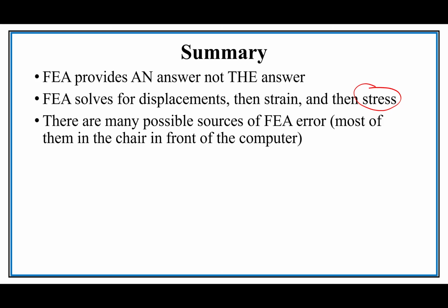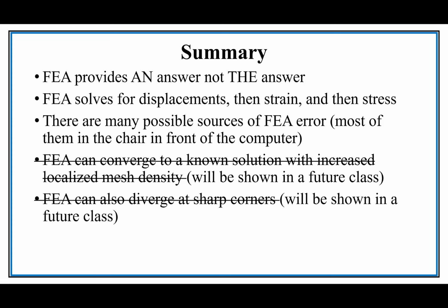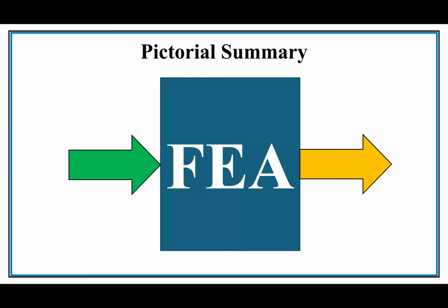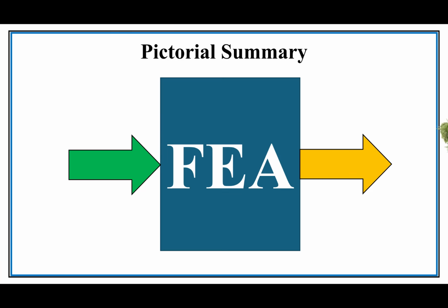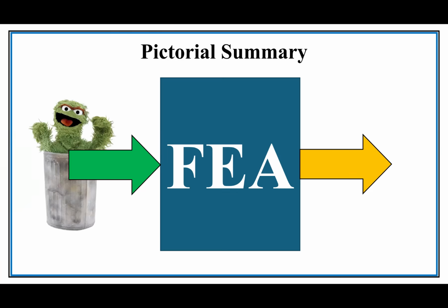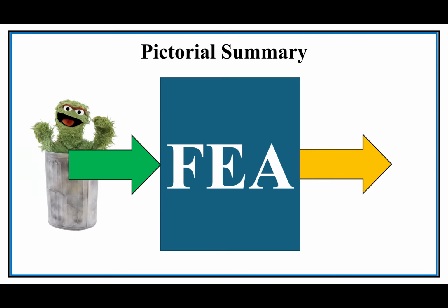And there's a lot of sources of error. Most of them are in the chair in front of the computer, right? You are the source of error. So don't think that what the computer says is gospel. There's some things we'll talk about in future classes I've crossed out here. But here you go. This is garbage in equals garbage out. That is our big thought. If you throw garbage into your FEA, you're going to get garbage out of your FEA.